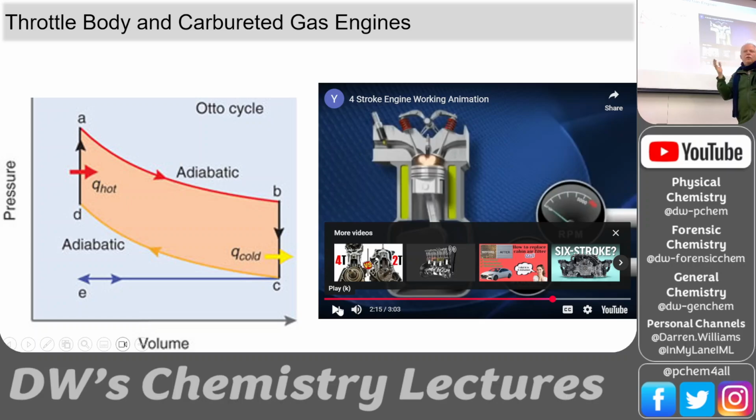That was more efficient or maybe better performance, I don't know. But sometimes you'll see that on engines or even on the backs of some sports cars, it'll say DOHC, and that's what it's standing for, dual overhead cams. Now that's a really important thing because the crankshaft is down here, the camshaft's on top. There's a timing belt that connects the two. Because if they get out of whack and they're trying to do a power stroke and one of the valves is open, all the gas is just going to blow out through the open valve and not give you a power stroke, and your engine's not going to run.